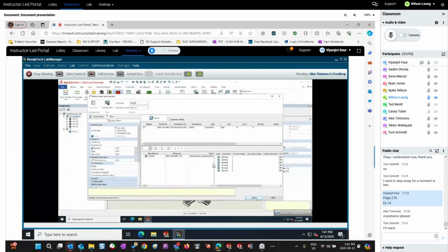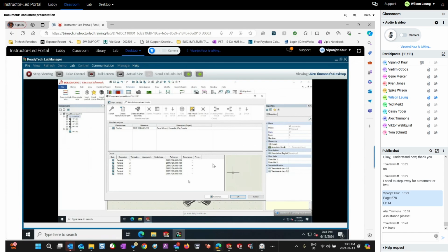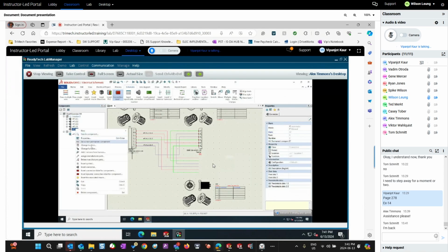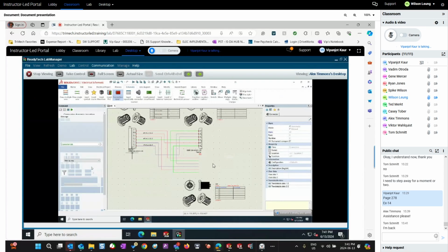Look at the right hand side, read the terminal column, terminal, right? Description is terminal, terminal, terminal. The description column, yes, click select and OK, so it doesn't have male pins or female pins. The type is terminal. Click OK, finish the command. Now you've got your connector X2 on the very left in the list. Let's right click on this and we will insert the symbol. So use your insert connector button. We would use a configuration.